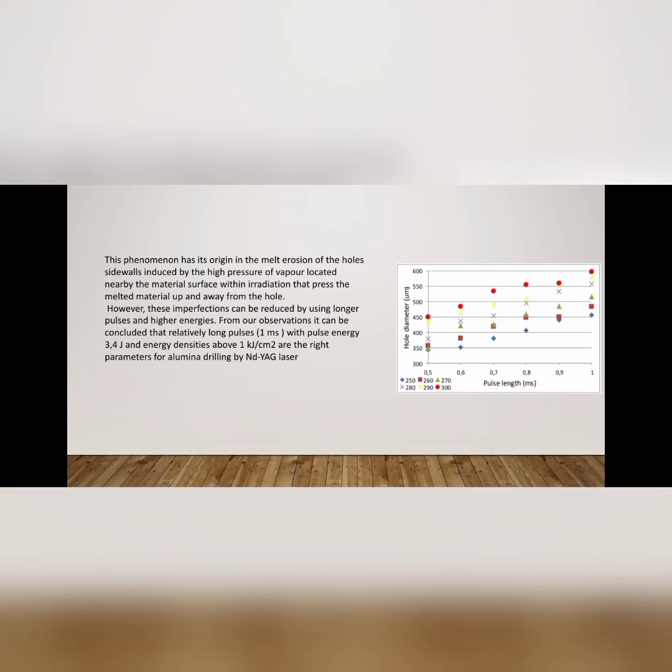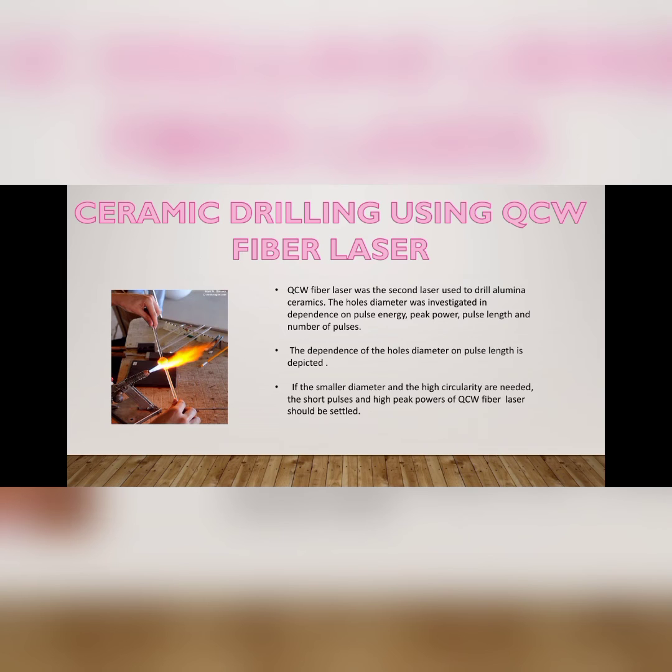This phenomenon also has its origin in the melt eruptions from the hole side walls, induced by the high pressure of vapor located near the material surface within the irradiation, which pushes the material up and away from the holes. However, these eruptions can be reduced by using longer pulses and higher energies and more pulses.